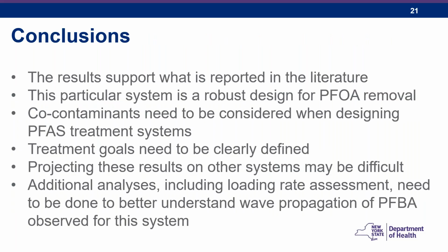And just quickly, the conclusions supported what we understood from the literature. This particular system was a robust design for PFOA. When you're looking to design, or to review a design for PFAS with GAC, you're going to want to be mindful of the co-contaminants that are in that system as well, and what the treatment goals are for that particular system.